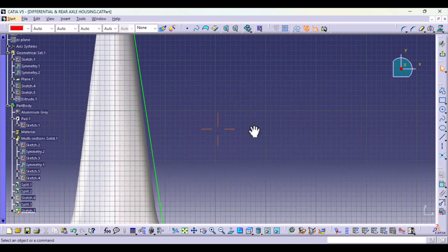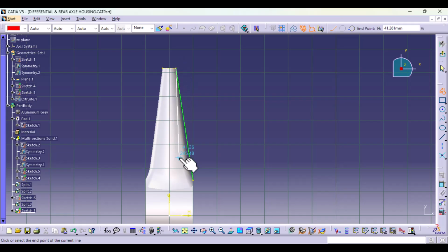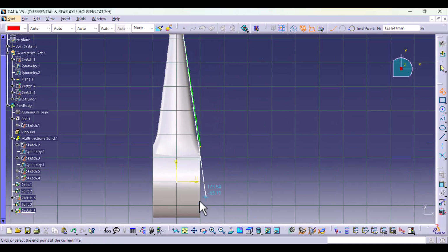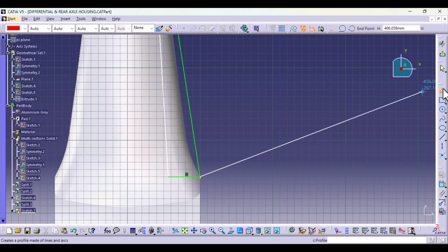The reason why I've waited to shell is because I want to see if I can create this. It's sort of a stiffener, but you cannot use a stiffener for this feature. It works well on, you know, walls. So we will use a pad instead. Something like that.